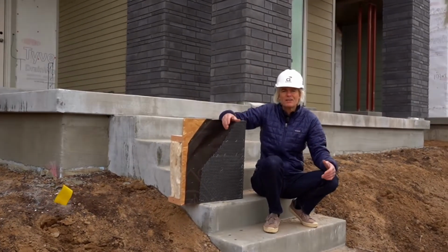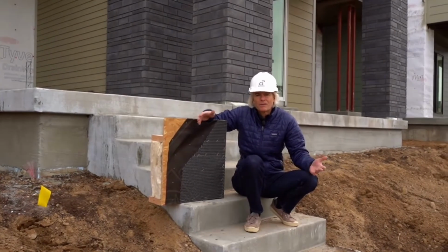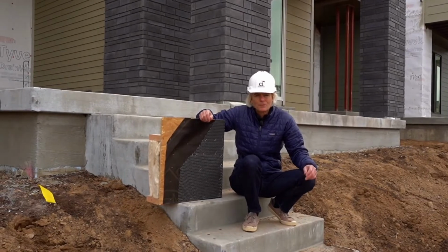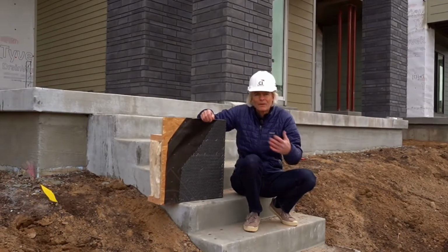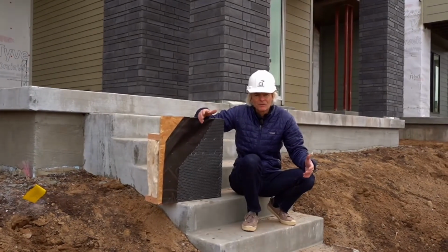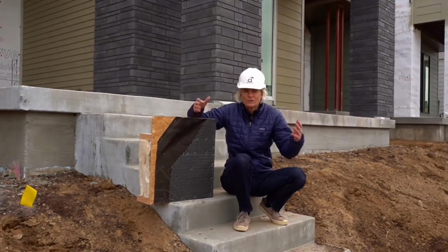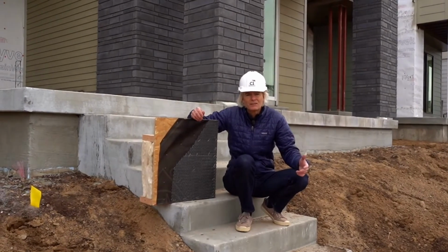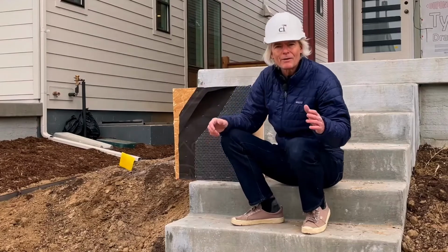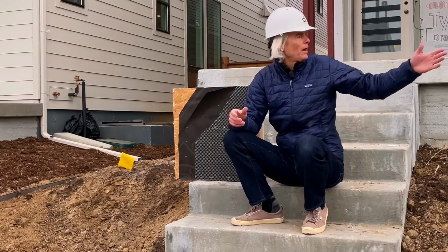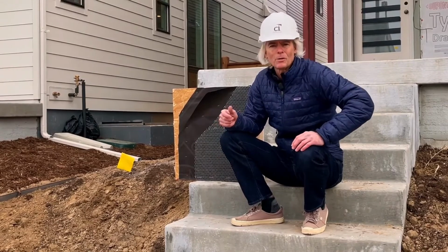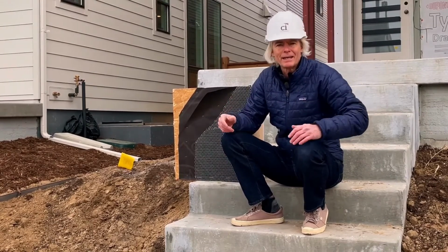In fact, I've seen failures on houses less than 2 years old where we've actually had to take them apart and figure out what's happened to it. And what it's telling me is if we had a rain screen out here and the proper application of different flashing details from base of wall to windows and proper detailing, we could have easily solved some of those problems. So let's just take a look at some of the houses that we've got around here and figure out what types of cladding that we have, and if we spot any problems or things that we can go back to the lab and take a next step at.